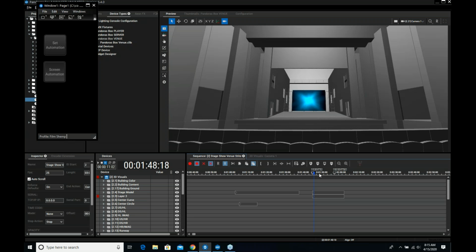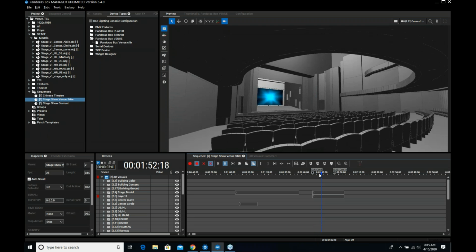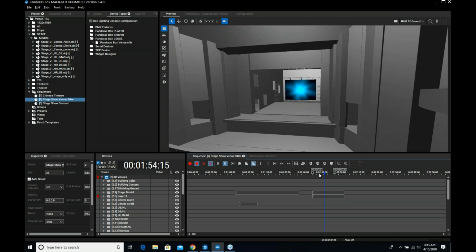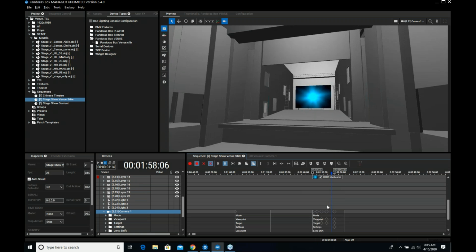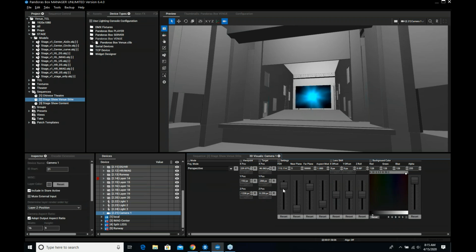Now, the one thing I will say that is very useful when you get into this, the first thing I typically do when you're doing camera movements, actually just right when you get into the camera, the default field of view is very low. I think it's something like under 10 degrees. The human eye is something like 150-degree field of view, but because we have two eyes and how our brain does it, we don't have fisheye.